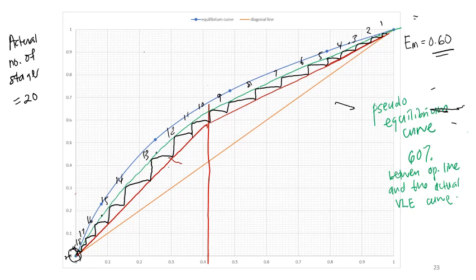So let's say after taking into account the 60% Murphree efficiency, you've got 20 stages. And in B, you have 11 stages, right? Ideal. So this is ideal stages. This is actual number of stages.